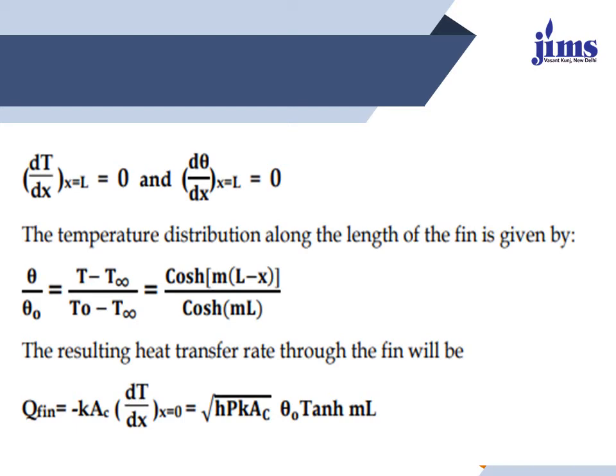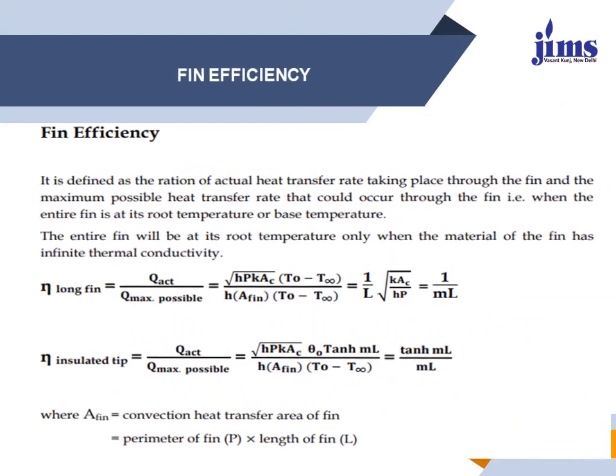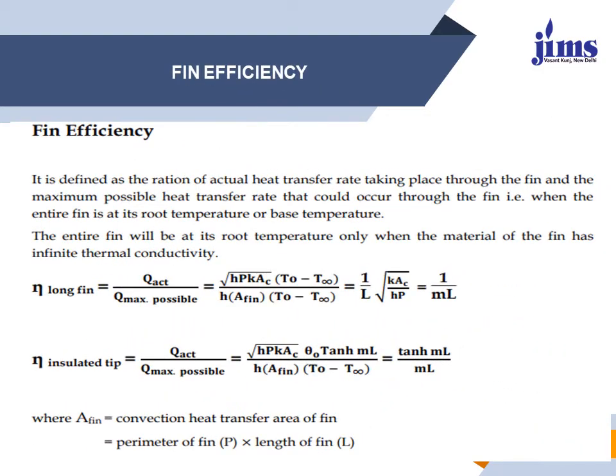So there are mostly two very important cases. Case number 1 means the length of the fin tends to infinity, and case number 2 is when the tip is insulated. My next topic is fin efficiency and fin effectiveness. These are very important terms related to the fin.